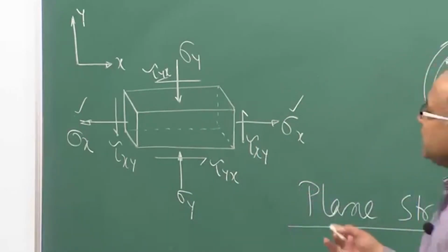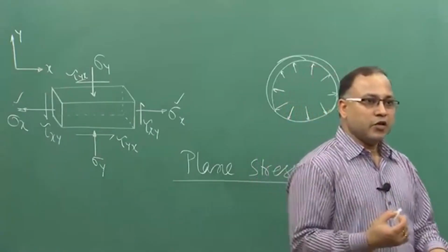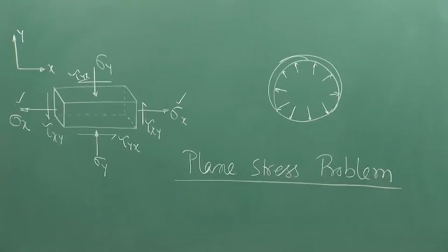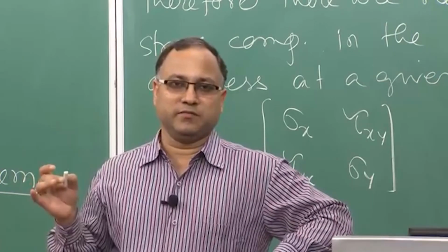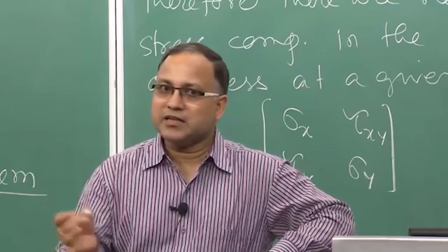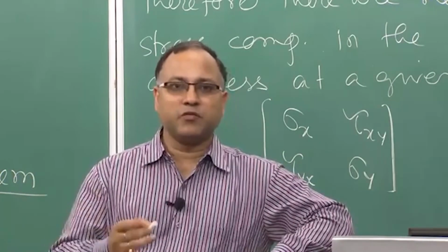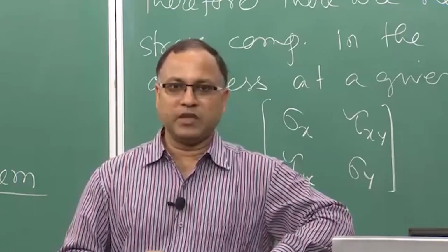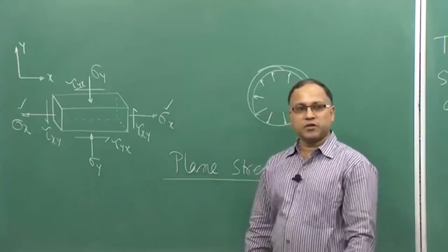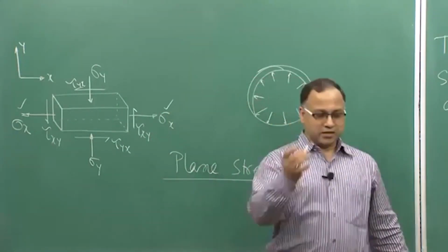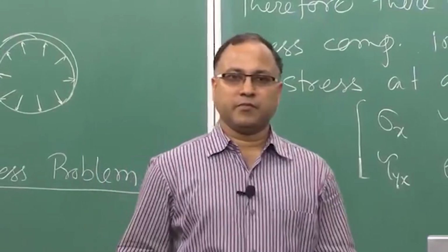So, what kind of nature are you getting from this normal stress? That is tension. So, as per our convention, the tensile normal stress is always positive, because that is in line with the sign convention we just talked about. The tensile normal stress will always be positive, because that satisfies the condition: on positive plane positive direction, on negative plane negative direction.